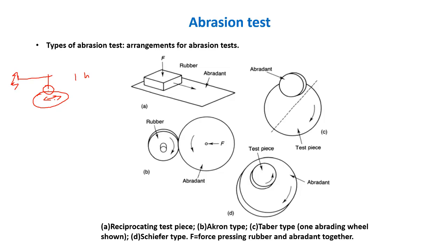So then what I do, suppose this is the original surface, and after some point there is a drop from there because the ball was reciprocating on the surface. I am showing the cross section. Then I check this with a profilometer.